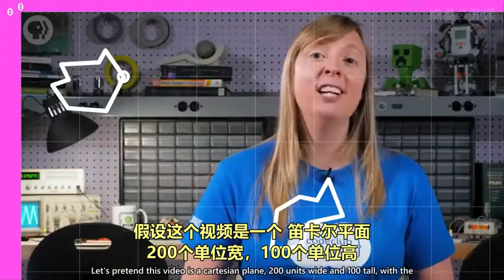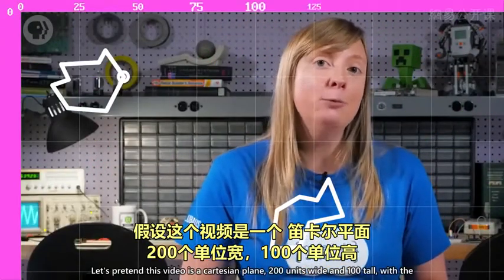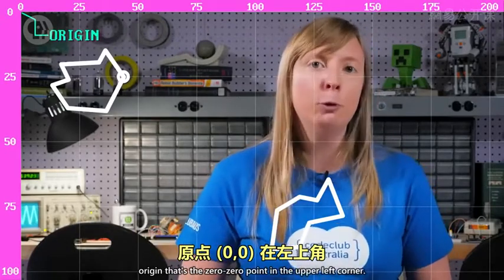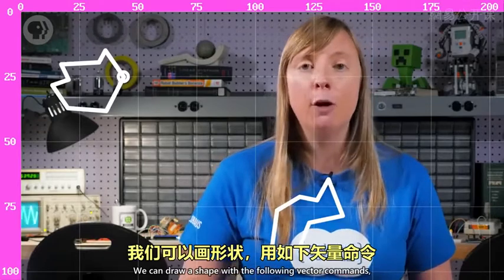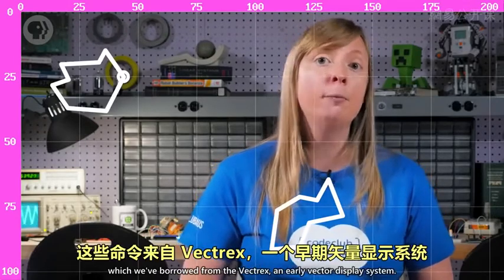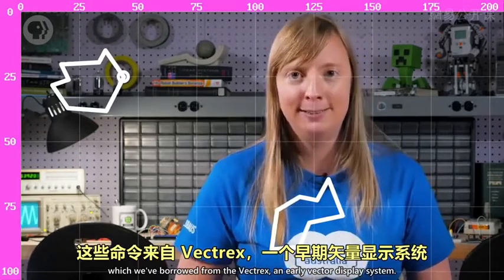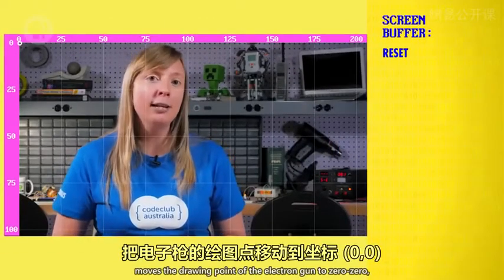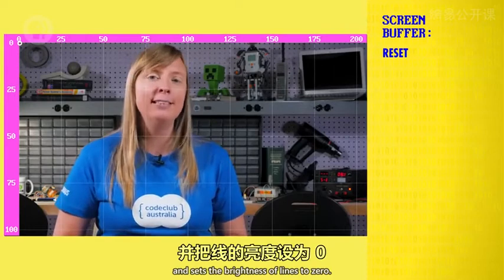Let's pretend this video is a Cartesian plane, 200 units wide and 100 tall, with the origin, that's the 0,0 point, in the upper left corner. We can draw a shape with the following vector commands, which we've borrowed from the Vectrex, an early vector display system. First, we reset, which clears the screen, moves the drawing point of the electron gun to 0,0, and sets the brightness of lines to 0.